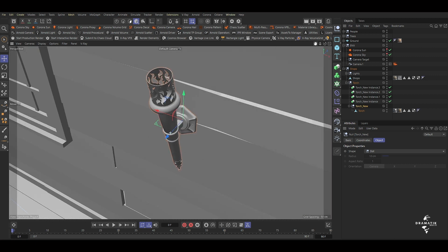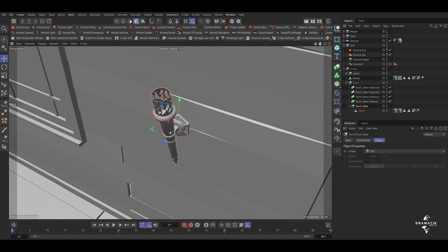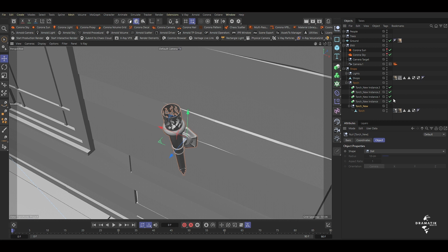To fill your screen with an element, just select it and then press S on the keyboard. Remember, when your mouse pointer is inside the viewport, if you do it on this other side, it will only identify the object amongst the list. So S inside here to fill the screen, S over here to find where the object is in this list, just so you know.